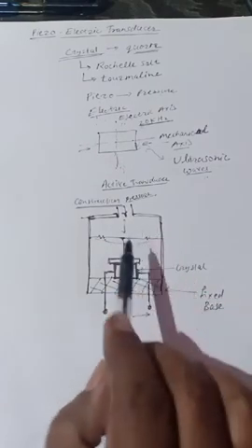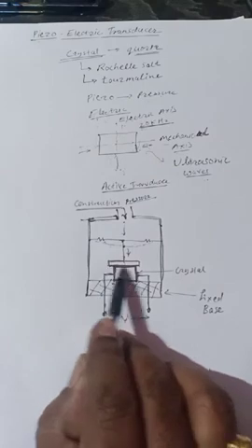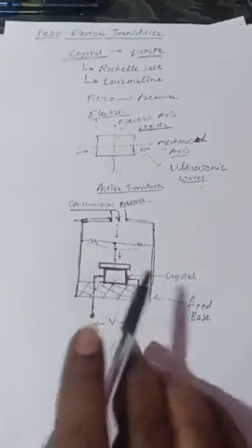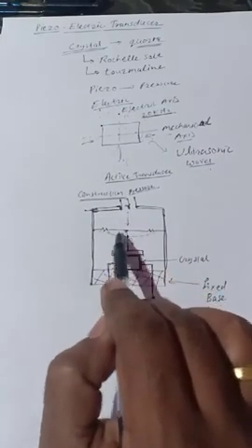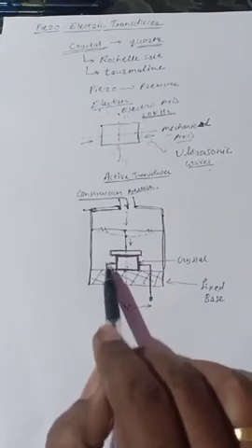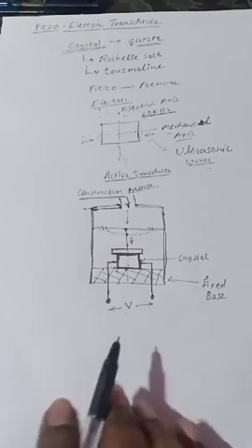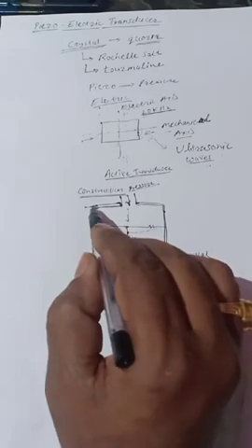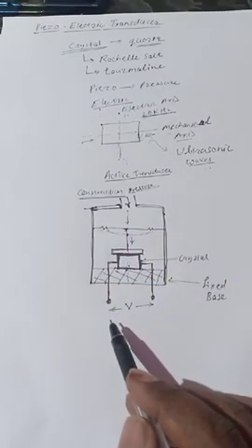Okay, so such type of crystal is placed between the fixed base and some support to create a pressure on this crystal using the diaphragm. If there is air pressure, the diaphragm bends down and creates a pressure over this, and it generates the voltage. Okay, so such type of another sensor we saw in a previous lecture, that is a capacitor transducer.